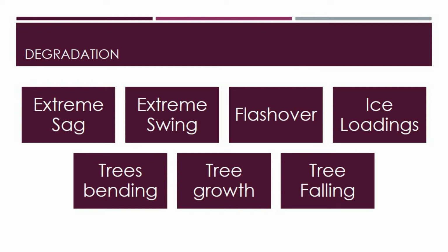Now, a right of way, unlike other distribution system assets, does not have a fixed life or expected end of life, because this is a special type of asset that's just a piece of land. And in order to accommodate distribution line assets in perpetuity, rights are purchased and held by the utility company. And when the utility acquires alternative circuit routing, a distribution right-of-way may be relinquished and the area abandoned by the utility company. When trees or bush growth extends within the safe electrical clearance envelope, the right-of-ways become poor or very poor condition in the case of overhead lines.